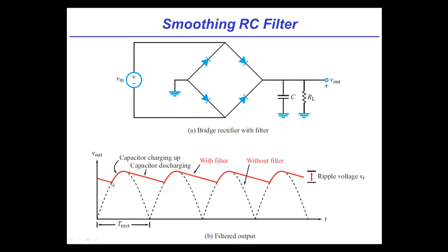So here, let's start at this point. All right, my signal comes up. Okay, I charge up the capacitor. Now at this point, my signal wants to go down, and this cap is going to start discharging. But it can't discharge as fast as the drop because you've picked the RC time constant so that it's much longer. Okay, I get it. And it's never able to discharge back this way because these diodes block it, because they're in the wrong direction. So it's only able to discharge through my load. That's right.